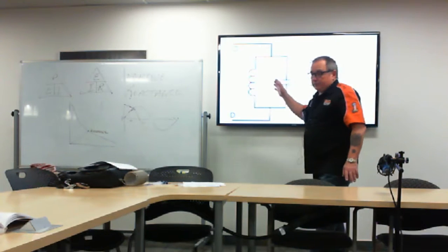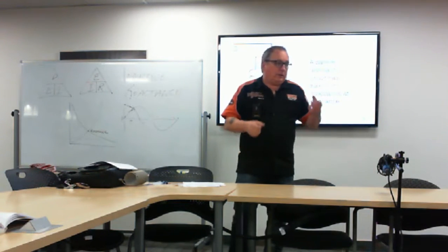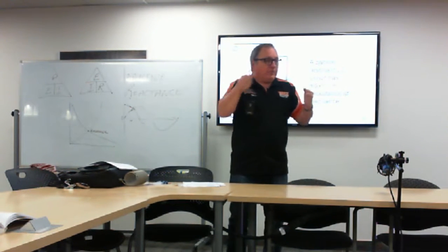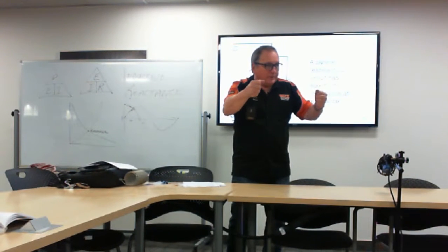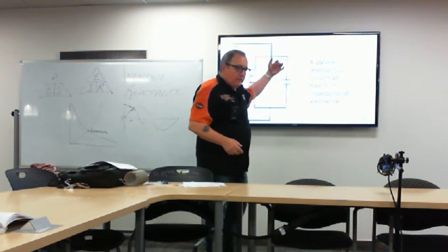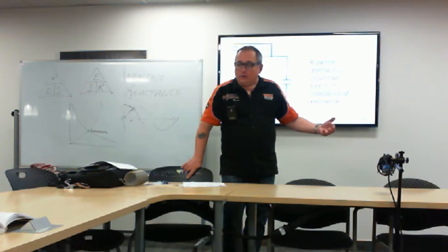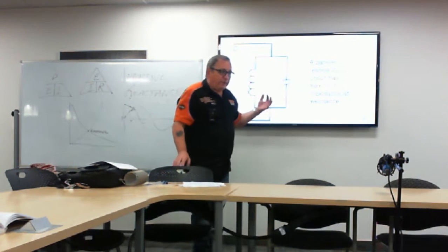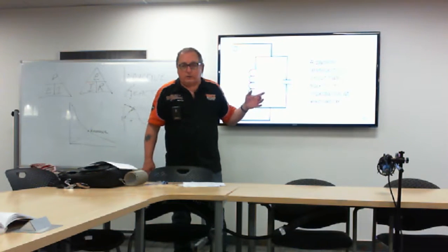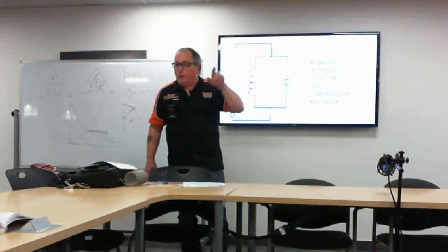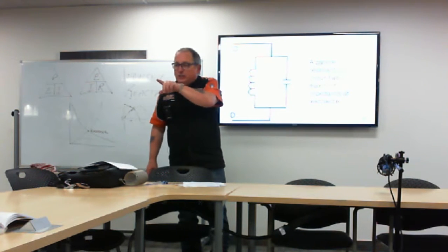That's the whole purpose of this lecture, about how the inductor slows the current and the capacitor speeds the current. So now we bring them into sync, we have resonance, and because we looked at those formulas which showed you inductive reactance and capacitive reactance, they're in opposite directions, correct? Inductive reactance is 2 pi FL, right? And capacitive reactance is 1 over 2 pi FC.